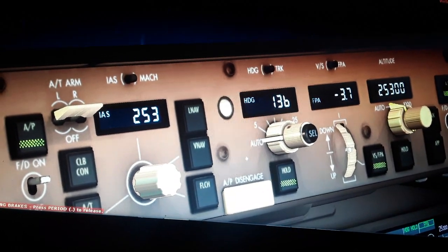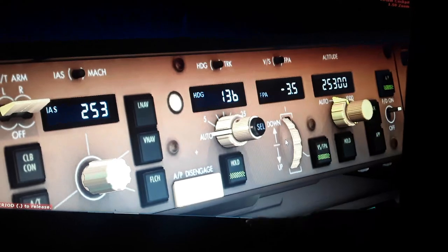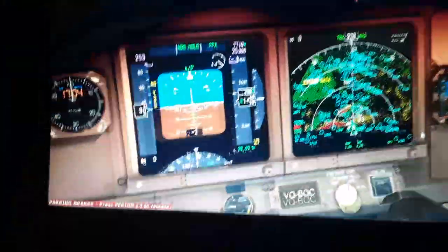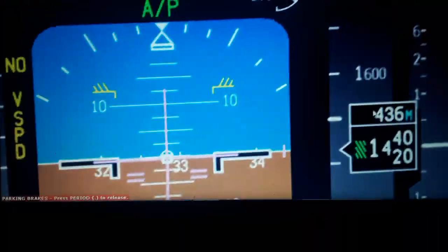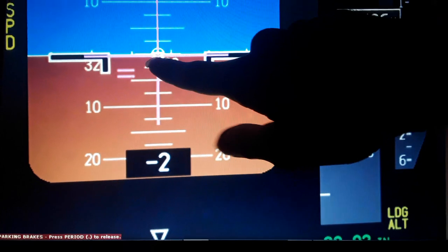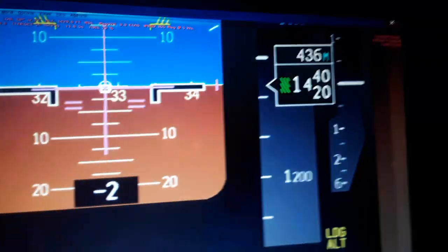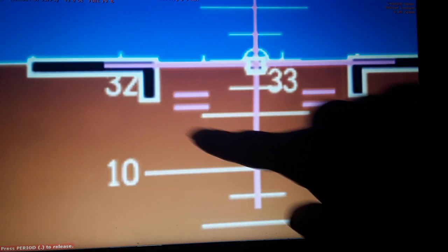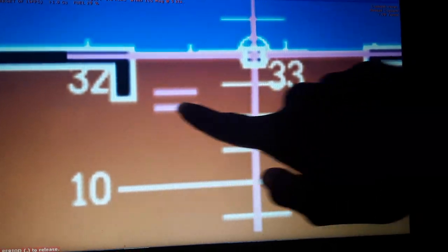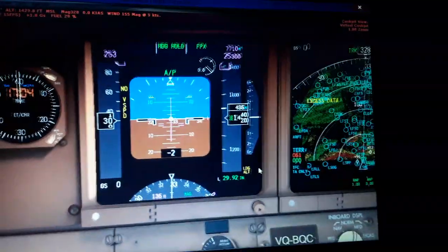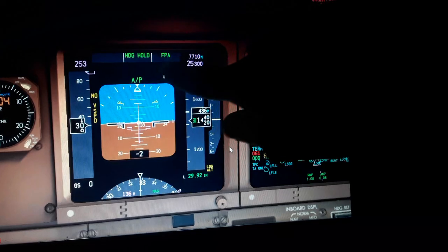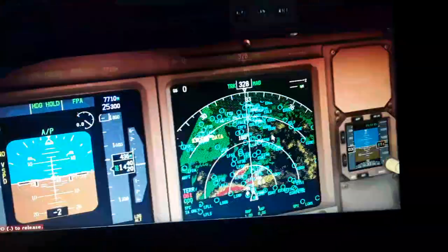Like a descent, like -3.5 degrees, you will see the slider moving. You will set -3.5 degrees descent rate for the aircraft to vertical flight or descend or climb. So you're gonna have here a minus below the horizon line here. In the altitude indicator, you can see these two purple lines between the -2.5 and the 5. So this is -3.5 degrees over here. With this mode, the FPA here and the heading hold.